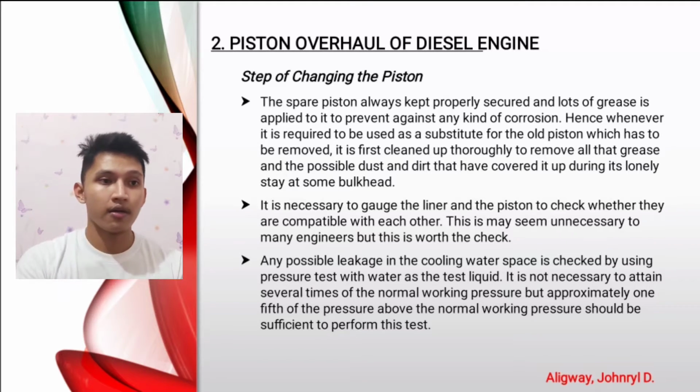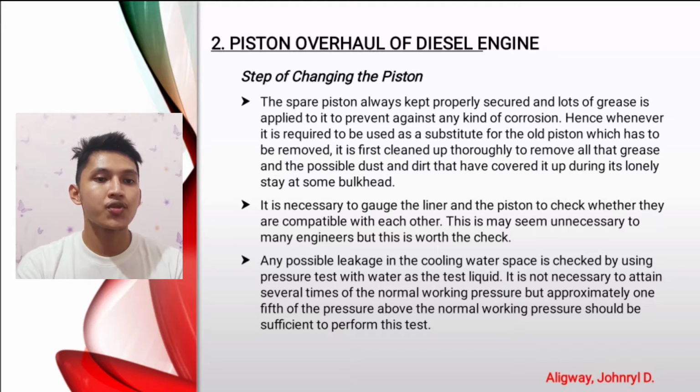So the first step of changing the piston is: the spare piston is always kept properly secured and lots of grease is applied to it to prevent any kind of corrosion. Hence, whenever it is required to be used as a substitute for the old piston which has to be removed, it is first cleaned thoroughly to remove all that grease and the possible dust and dirt that have covered it up during its lonely stay at some bulkhead.